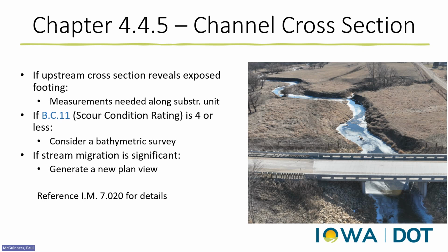With channel cross sections, you will be performing, or at least looking at, channel cross sections. And this slide also shows what would trigger the need for more detailed measuring or inspection. So if you're measuring the upstream cross section and the depth of the mud lines per the plans, or you can see exposed footings, then that triggers getting down there and measuring along the length of that substructure unit to verify how much of it is exposed or even potentially undermined to condition code BC11.